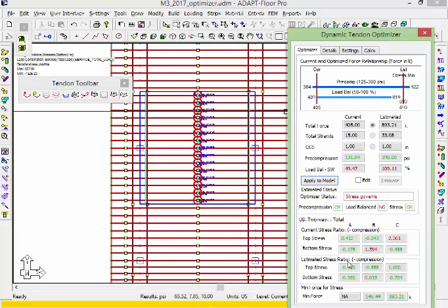However, our estimated stress ratio would be 1 at support. Here, this section cut C, which is the interior support, and it would also be 0.033 at the bottom stress. We were having an issue also at the bottom stress. So using this value would violate the balance loading, but it would still maintain the allowable stress and pre-compression when we look at this individual span. So we'll go ahead and we'll apply that change to the model.